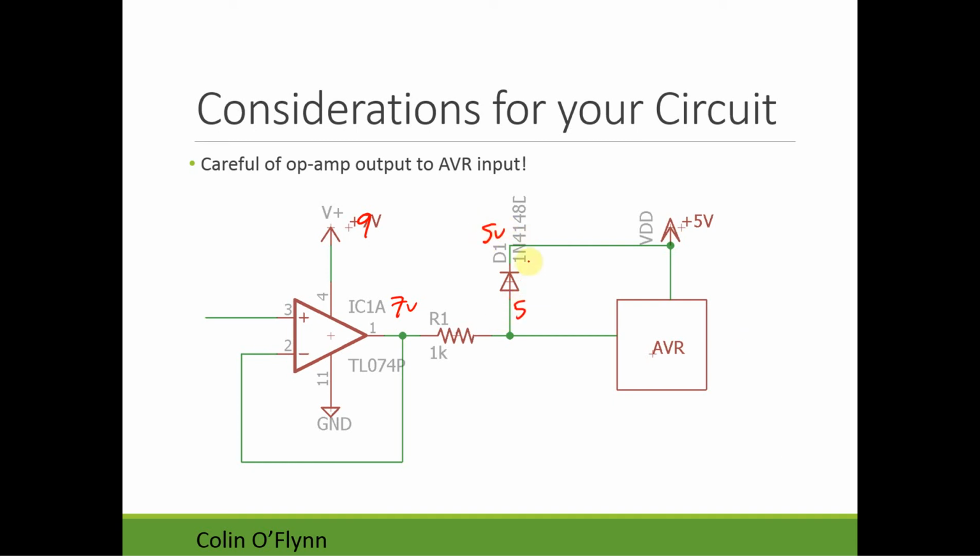So above, if you remember, diodes start conducting when there's more than, it varies on the diode, but around 0.5 to 0.9 volt difference. Normally we say about 0.7 volt difference here in the correct orientation, which there is. So this pin here will now be limited to only going to 5.7 volts because it'll start conducting and feed power into the supply. To use this, the only really critical thing is that I have a resistor here.